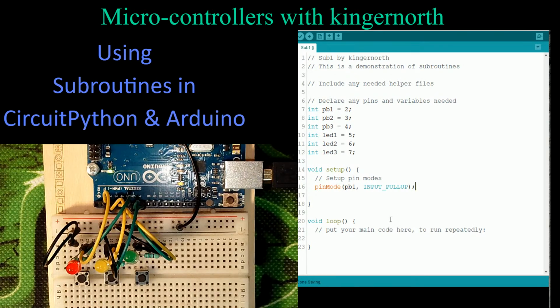I'm going to take that 5 volts and change it to ground. I'm going to run it right to ground. The resistor to limit the current so we don't burn up the board is actually inside the chip itself. And by using this term pull up, it turns that resistor on to allow it to be working. So if we were to take a meter right now and connect it to that input pin, we would see there's 5 volts on there. And all I'm going to do is ground it when I'm ready.